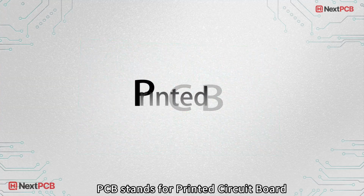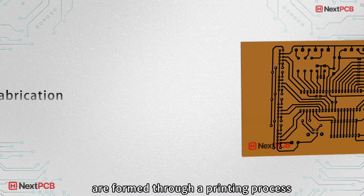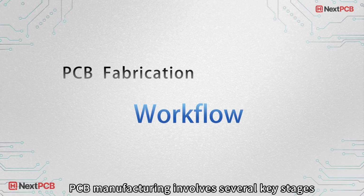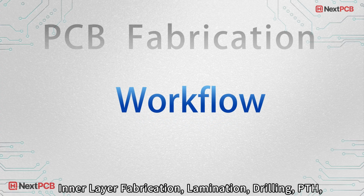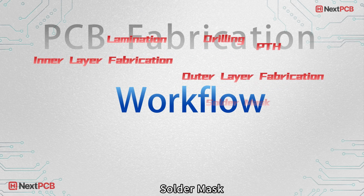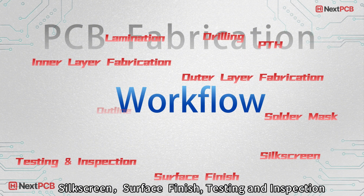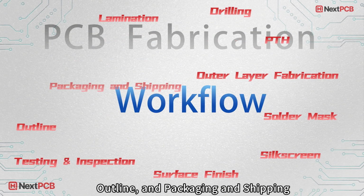PCB stands for Printed Circuit Board, and printed simply means the circuits are formed through a printing process. PCB manufacturing involves several key stages: inner layer fabrication, lamination, drilling, PTH, outer layer fabrication, solder mask, silkscreen, surface finish, testing and inspection, outline, and packaging and shipping.